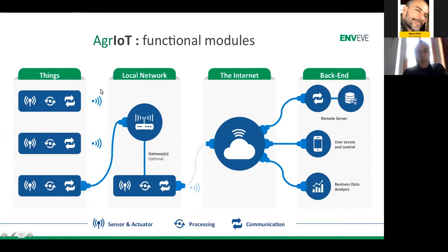Those sensors, in the Internet of Things, are normally connected through RF. So you have a micro radio, which is communicating with a local repeater or a local gateway, which is basically a little computer, the size of a mobile phone and with the power consumption of a mobile phone. Sometimes they are also connected through cable. Normally the cable ones are the older.